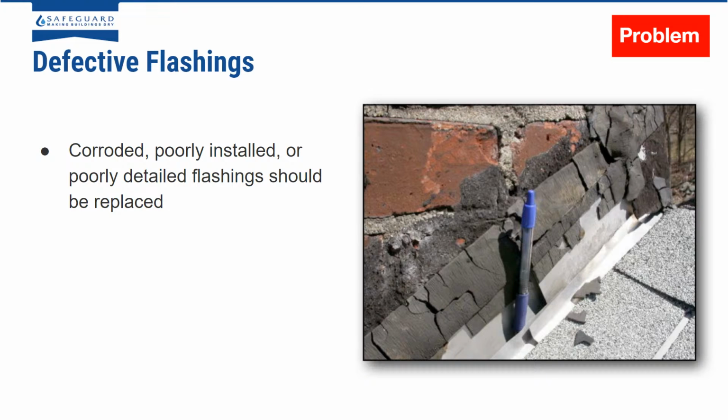Defective flashing. On older properties that have not had their roofs looked at for quite a few years, you quite commonly find that the flashing is corroded or even been poorly installed, and simply this should be replaced and rectified. So in this situation, it's best to get some form of roofing specialist in.